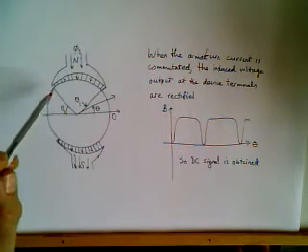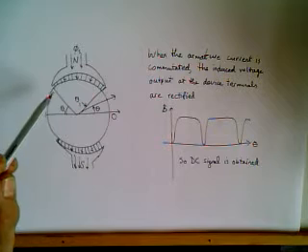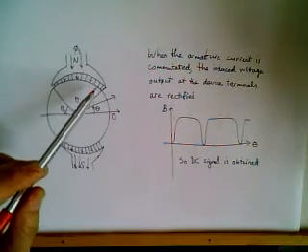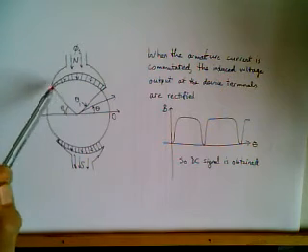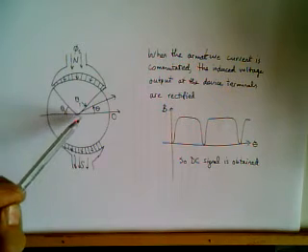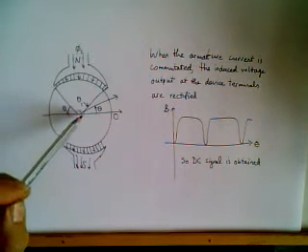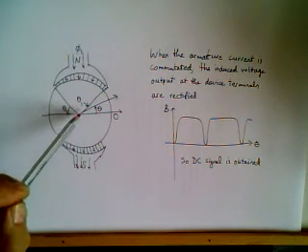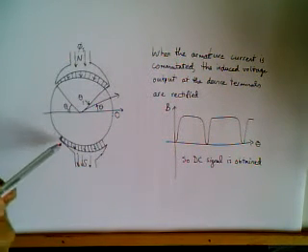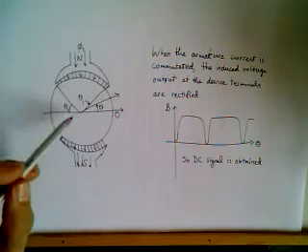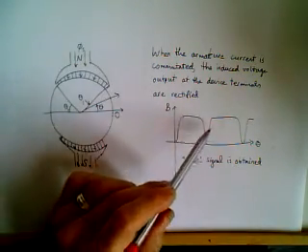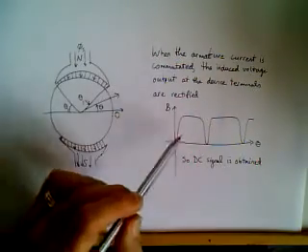So the induced voltage, which is the time derivative of the flux linkage, is positive here, negative there. But DC machines always have commutators, so that the wires are commutated such that when the flux is negative, the polarity of the wire is reversed, etc. So we obtain a rectified output at the DC terminals of the machine.